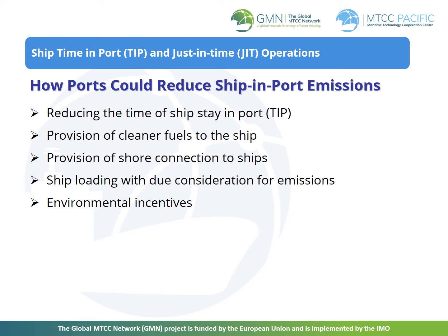There are a few effective ways of reducing ships' fuel consumption. Two main examples are operating the ship at reduced speed during passage by just-in-time operation. Trim optimization and ballast water management can contribute to significant energy saving. Port operation has impacts on both of the above.